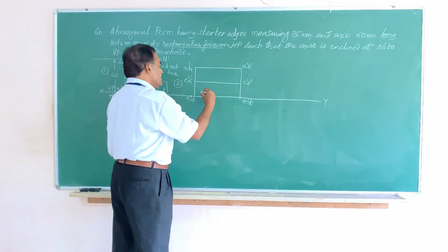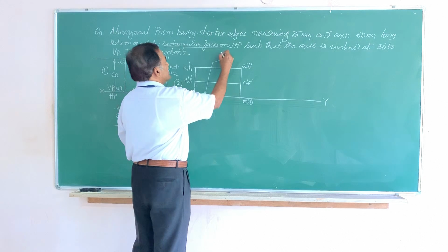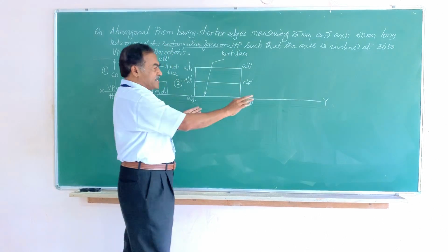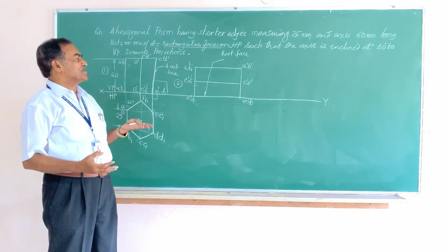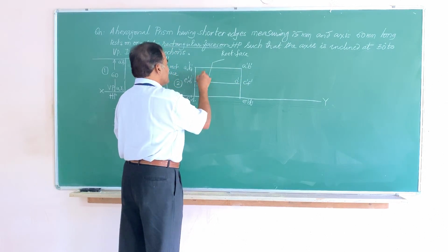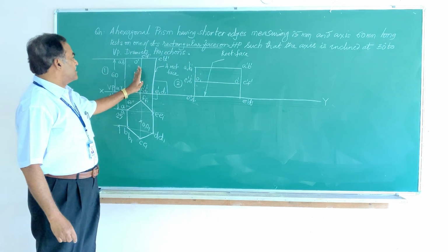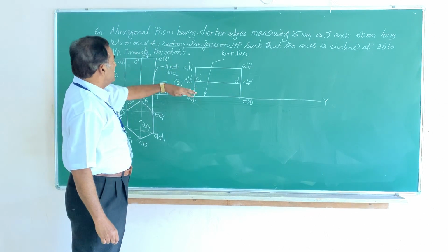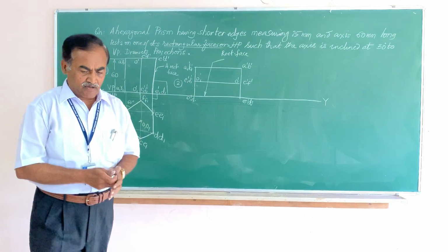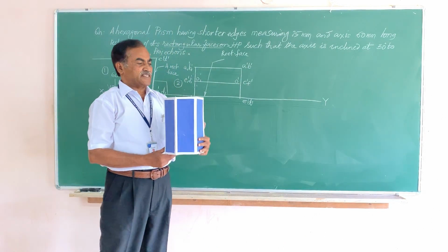Friends, you can observe here, now this line which is on XY or on HP represents a rectangular face, and this rectangular face is on XY, or in other words it is resting on the HP. So let me also mark O dash and O1 dash, the axis of the solid. After getting the front view, by shifting this figure and drawing it on a line on XY, let me get the corresponding top view. I will show you how it looks. So you have a figure like this.